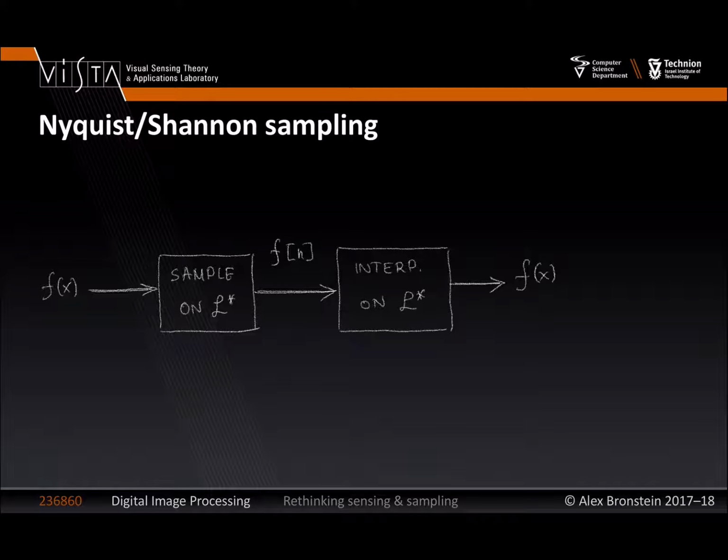Okay. So let me massage this model a little bit. I will bring it to our terms of inverse problems. So basically, we have a prior. We can think of it as a subspace prior. We assume a priori that our signal belongs to a subspace of L squared. It's not any square integrable function. It is a function that can be written as a linear combination of these sincs, which is equivalent to saying that it is band limited, right?